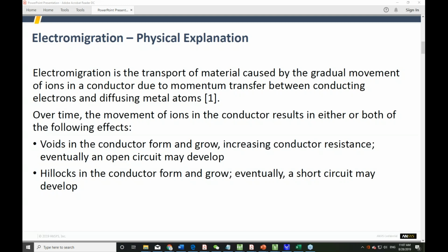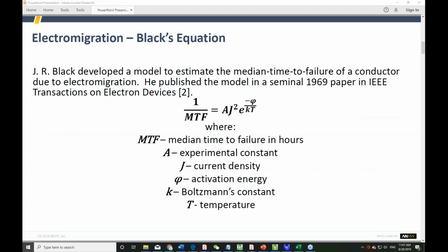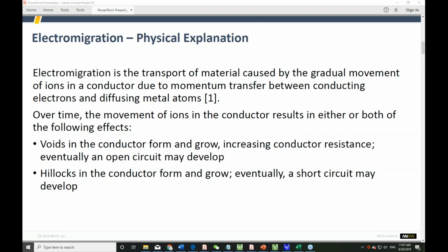So, as we said, electromigration usually takes place in solid state metals when the metals are stressed at high current densities, along with high temperature above about 100 degrees Celsius. This phenomenon results in steady change of conductor dimensions, causing damage in terms of voids or hillocks in the integrated circuit. The term electromigration was created by Professor Hilbert Huntington in the late 1950s because he did not like the German use of the word electrotransport.